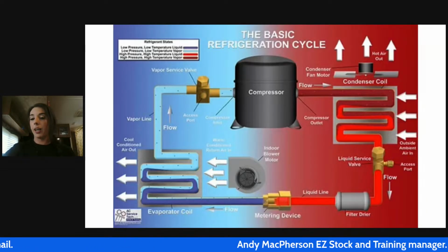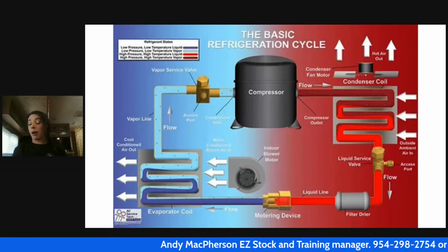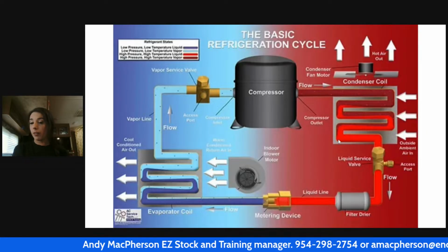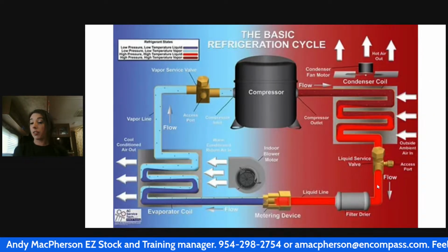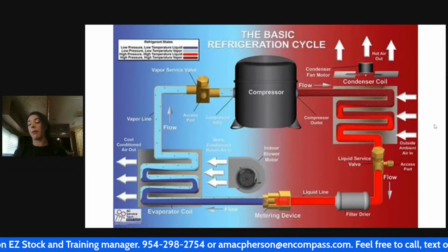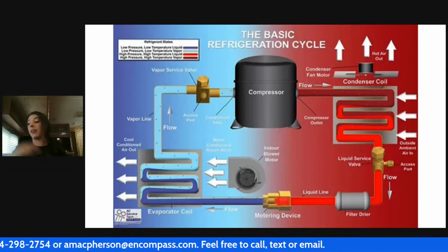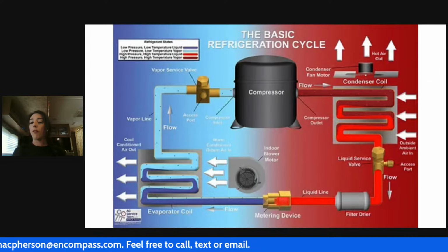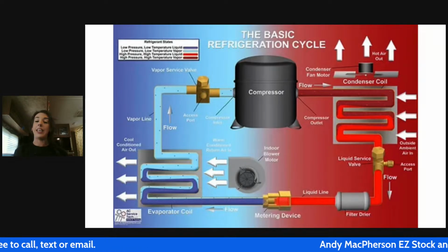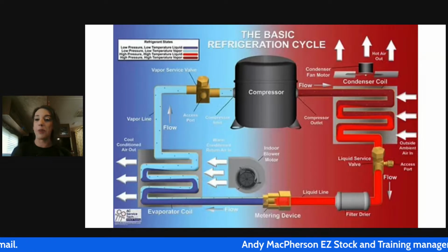or swampy, right? At the same time, outside air is coming into the condenser coil and it's helping with that phase change because it's, again, cooler usually. Sometimes we have situations where our condenser is rejecting heat that is cooler than the outdoor ambient temperature. But for the most part, we have cooler air. So what's that going to do? That's going to aid in that heat transfer too, via a different method of heat transfer.